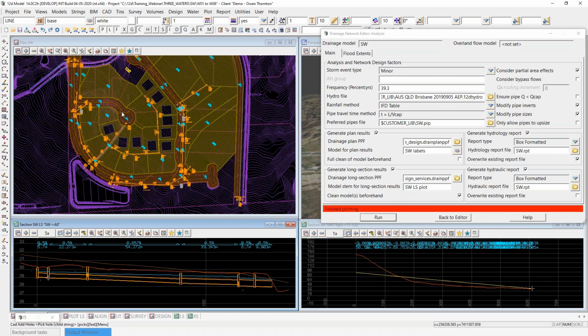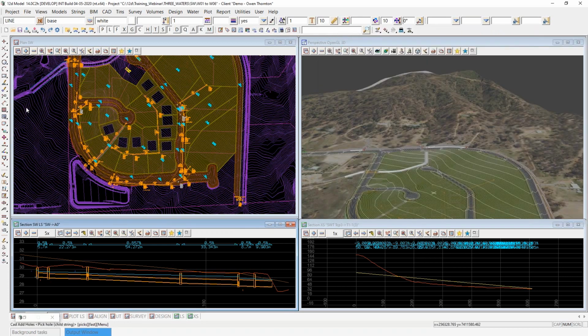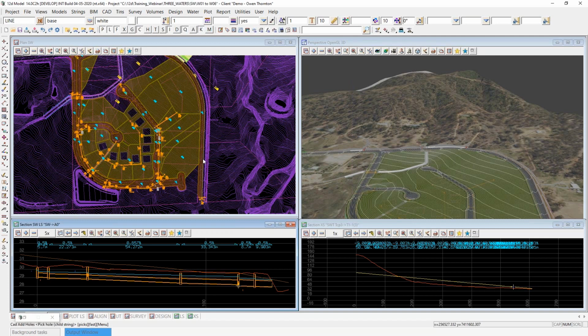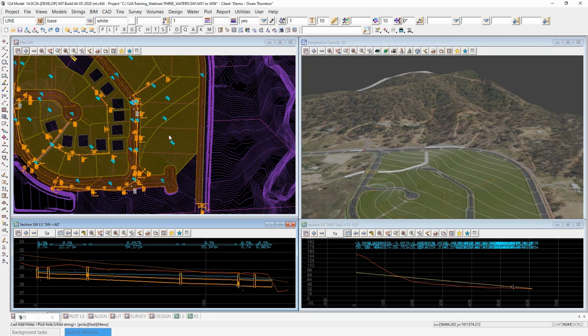But what I wanted to show just quickly with the catchments, a couple of little tips there. What I mean with the CAD toolbar, this is the CAD polygon toolbar, and it's specifically this freehand and boundary polygon options that I use a lot. Say you wanted to draw another polygon from this set number 2. Use this eyedropper same as icon to populate this CAD control bar at the top. Eyedropper, click on that polygon there, and that's populated the model name and the color and all of that. So you can just begin drawing polygons in that same model.